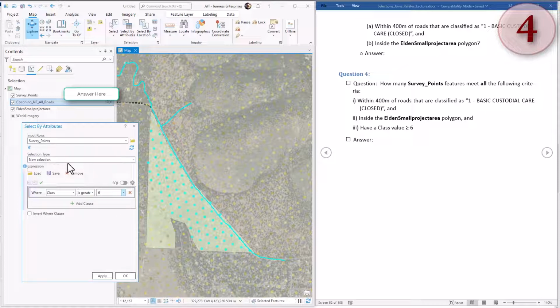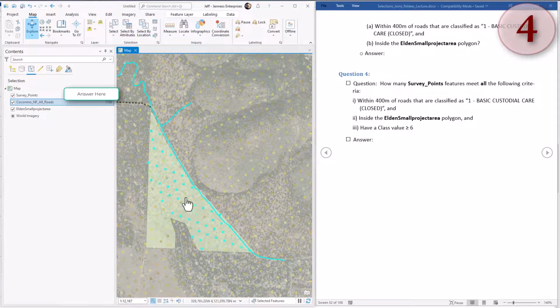And it is not a new selection. That's important. We're taking a subset of these currently selected points. So it's going to be a select a subset. When I hit OK, I should see some of these selected points become unselected, but nothing new out here becomes selected. Hit OK, and it did just what I want. And the correct answer is up here in the selection pane again, or in the attribute table. All right, that's all there is to it.